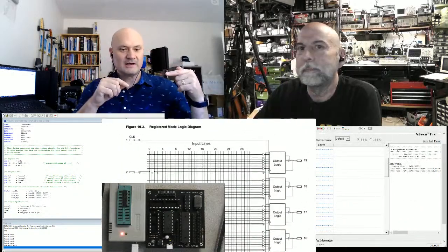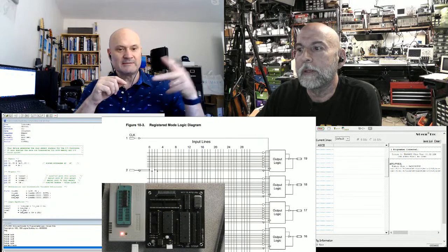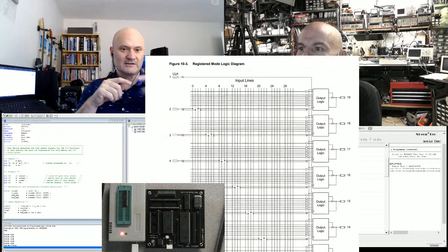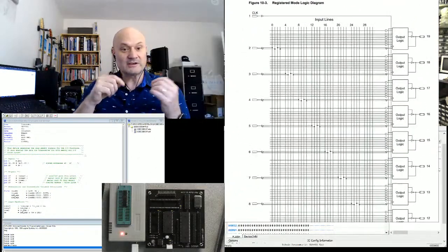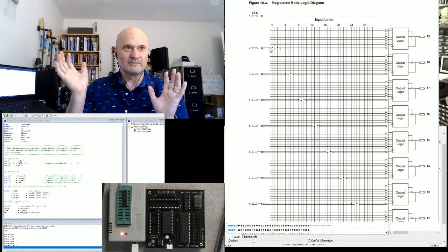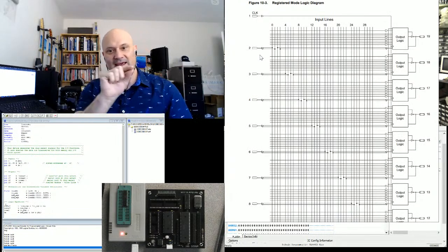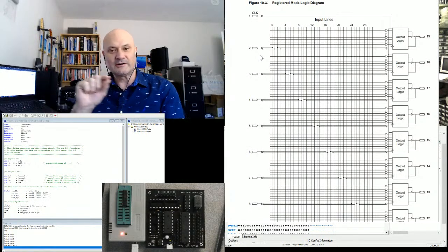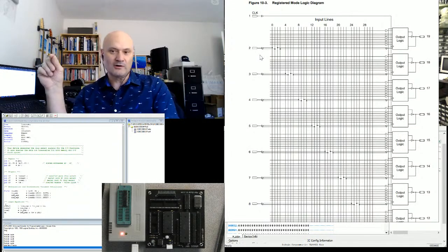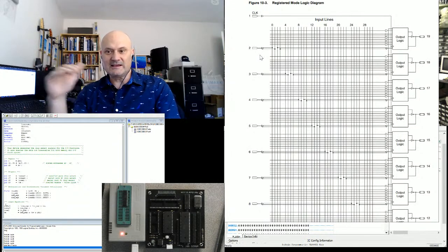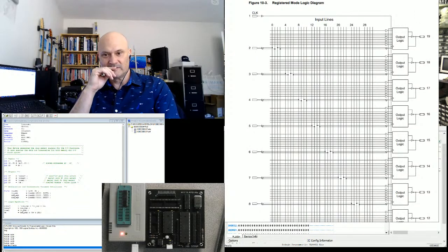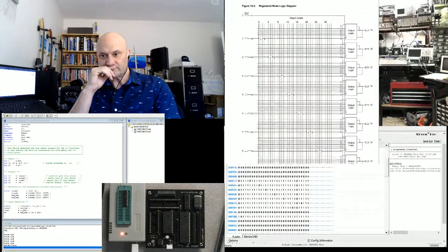You've got an input true and an input complement. Like you're saying, there's an inverter or it's a differential drive. Right. So you can take an input, or you can take an input barred. So you can get whatever you want. True or complement, and wire AND those together, or wire OR, it's basically a sum of products, right? Is that what you call it, Bill? Yes. Yeah, that's what I would call it.